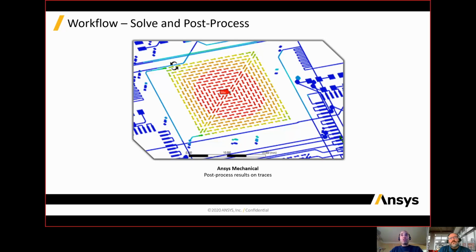So remember, the structural part here might not be the biggest deal for me, but the thermal is really important. I'm literally using the board as my heat conduit, and I'm putting a lot of vias under that component specifically to create a heat sink to the other side of the board. The trace reinforcement is basically the killer app for that. There's no better way. It's faster and easier and simpler, and it just looks cool.